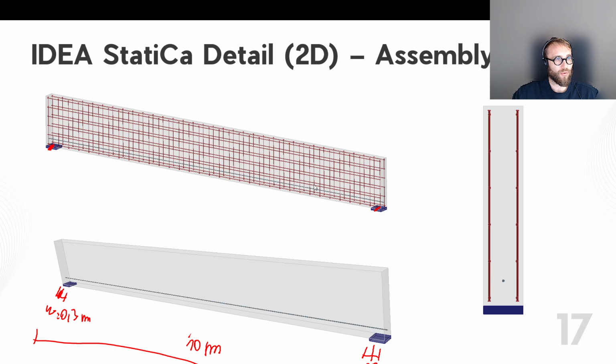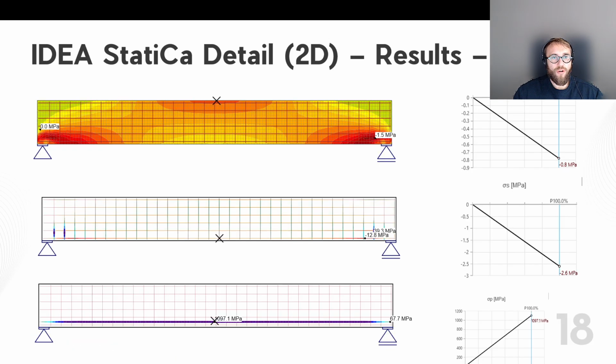This is the higher level of the modeling, with material nonlinearity and tension stiffening, with consideration of some bond effects that are also affecting the results, and changing the behavior of the whole beam. Okay, so once we analyze the beam on the 28th day, at this stage there is prestressing plus the self-weight. This is the first load case, or first construction stage, where it's just the self-weight plus prestressing.